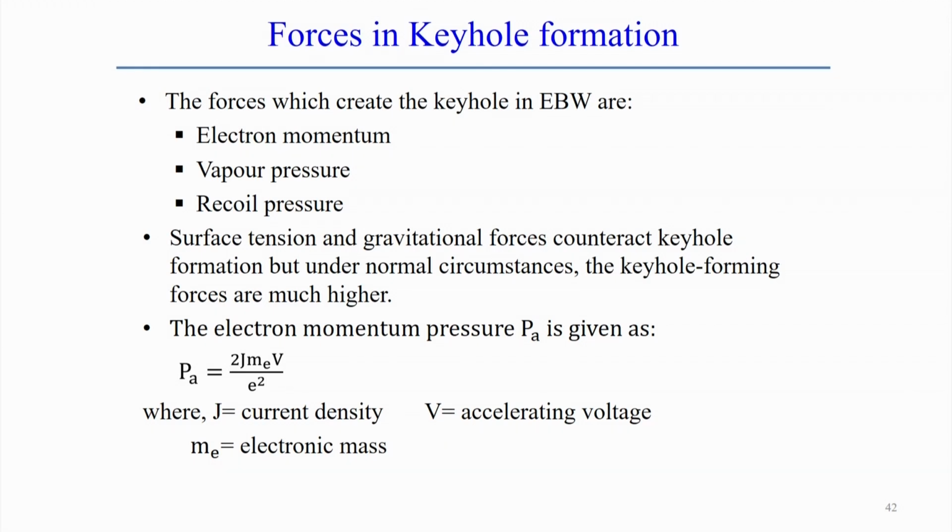Therefore, when you try to explain the mechanism of keyhole formation, we can compare the surface tension force and the gravitational force. When they are equal with respect to each other, they actually open the keyhole and keep the keyhole alive. That depends on the balance between the surface tension force and any other gravitational forces.